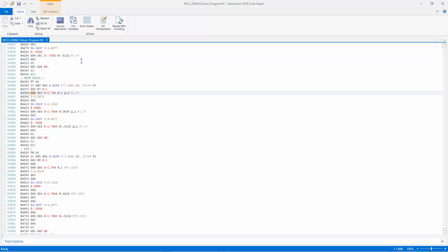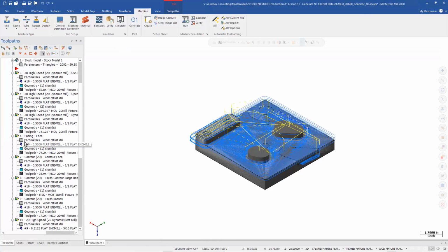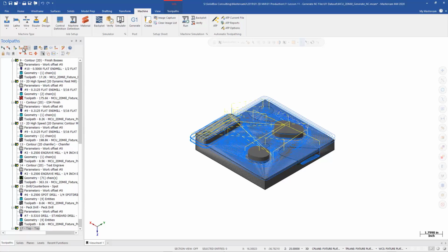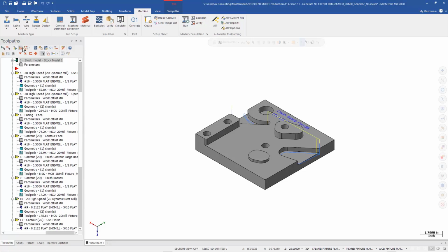You order these toolpaths. It's a good idea to do it back in Mastercam by simply dragging and. So if we decide, for example, the tracing operation needs to happen before, we can simply drag it up and reorient them inside of our toolpath manager. And then if there's any, we can rebuild those and make sure that everything, including the stock. So that's my recommendation to you, is to make sure that you do as much as you can in Mastercam in the CodeExpert in order to modify and edit the code.